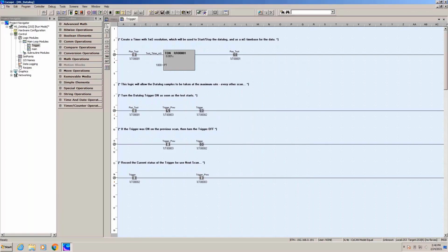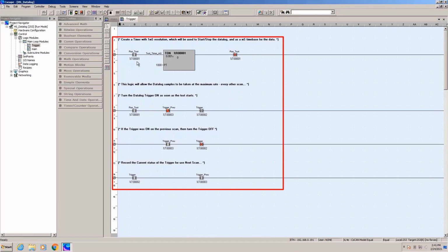From the standpoint of the new data log group that we just created, it's not actually data logging yet, because that's done on demand. Whenever this T1 test is initiated, that bit is started here. Okay, I've turned on the debug mode, and I'm going to trigger this test. And I happen to have a button on my XL4 that you can't see that I'm going to use to trigger that test with. Okay, so you can see that bit in that test turned on for a second.